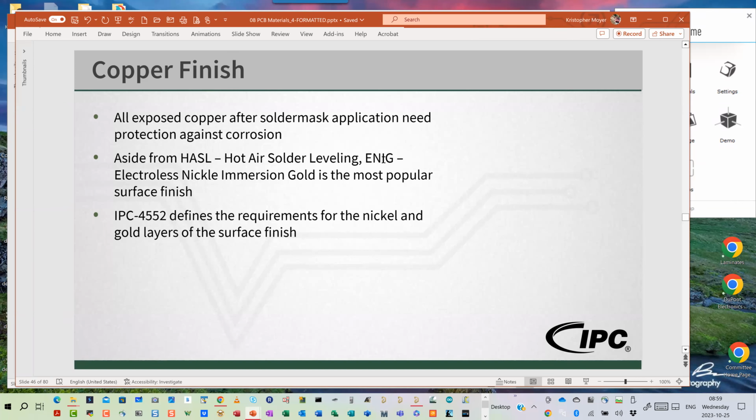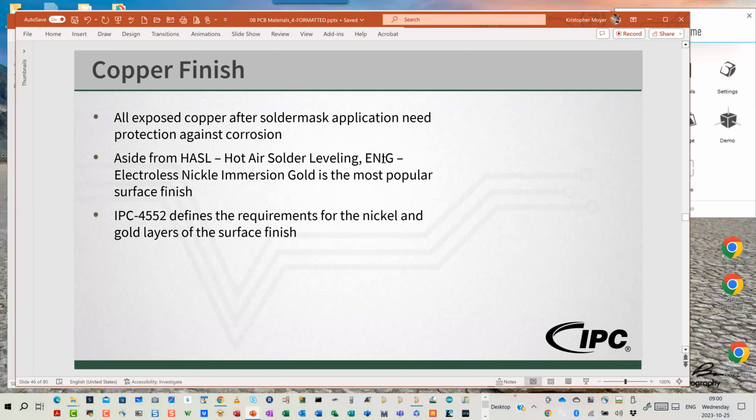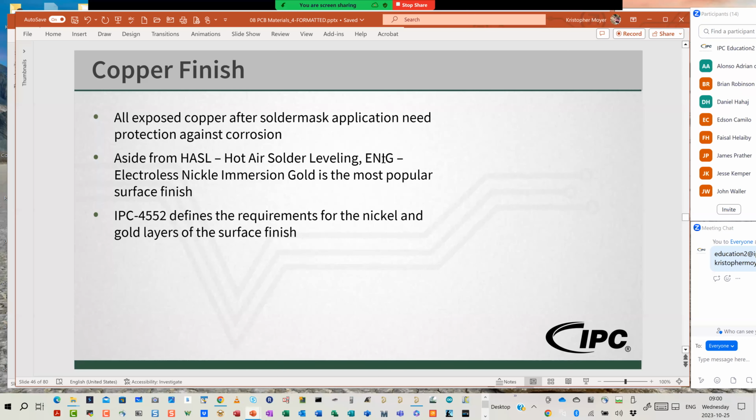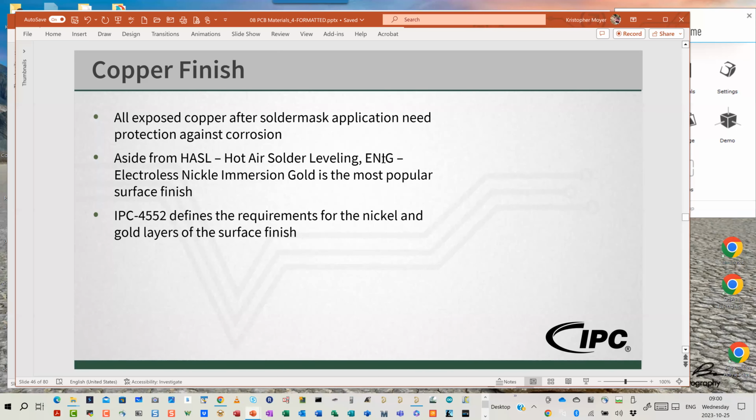But now we're talking two precious metals instead of one, plus instead of a 27 bath process, it becomes like a 32 or 35 bath chemical process to apply, treat, neutralize, et cetera, over and over again. We'll look at that next week during manufacturing. But yeah, I pretty much stick just to HASL or ENIG if I'm going to do one.